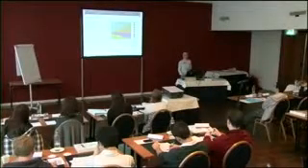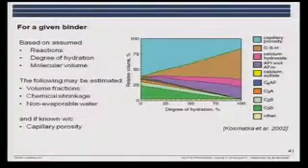So for your material, if you have this information, you can do it better than just using the Powers model. And if you know the water-cement ratio, you can also determine the capillary porosity at any degree of hydration.